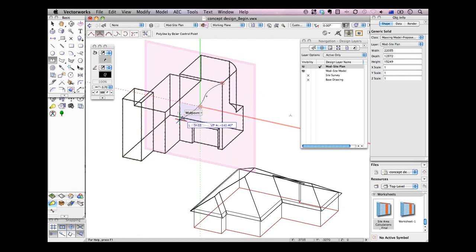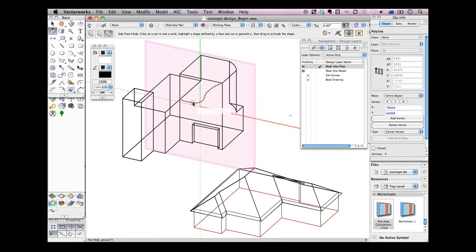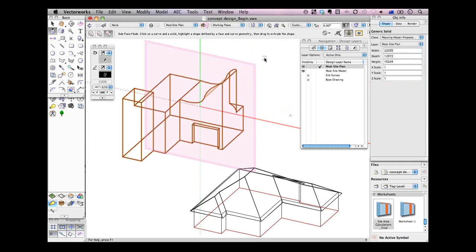Okay. So here's another one. Can you develop a quick roof for this model? Well, I could have done until I did that curve on the top of that funny building, but it depends what you mean by a quick roof. So, for example, the building's now all over the place with lots of different planes, but if it was still a planar roof, then you could probably use things like a rectangle and then create a roof from that object. Or if I wanted to, I could use tools like my split tool.